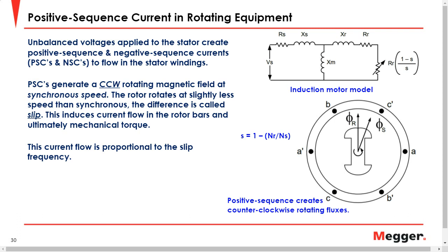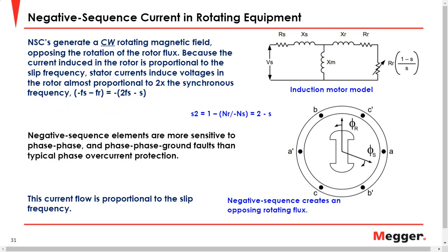That's when we are talking about the slip as it refers to the positive sequence component. But when you have a negative sequence, now we are talking about a voltage system that is producing a magnetic field, or more accurately the maximum of a magnetic field, that's rotating in the direction opposite to the rotor at the same 3,600 RPM.